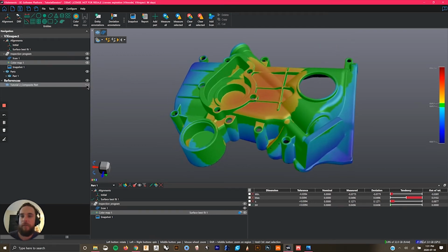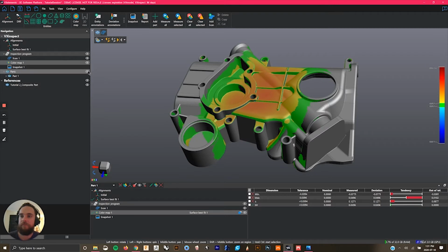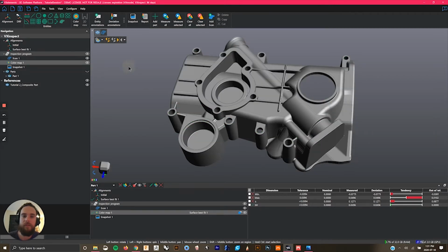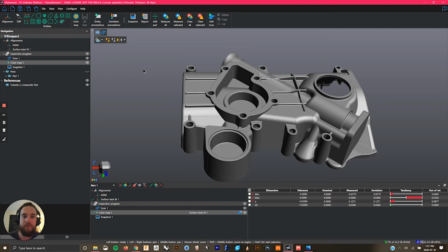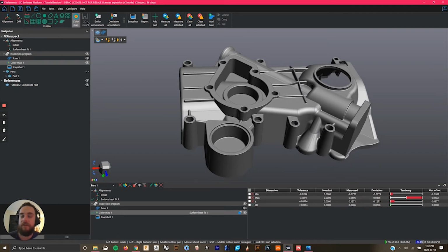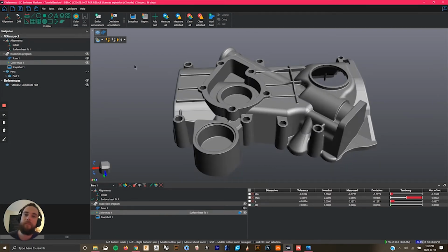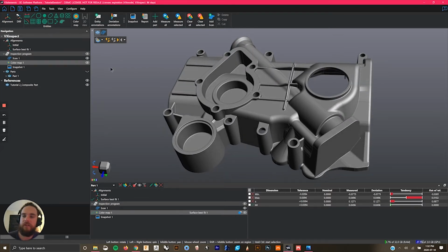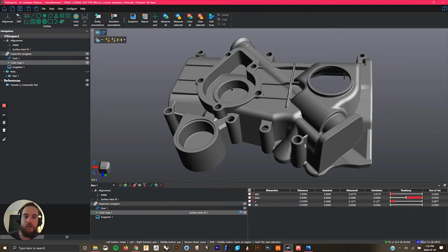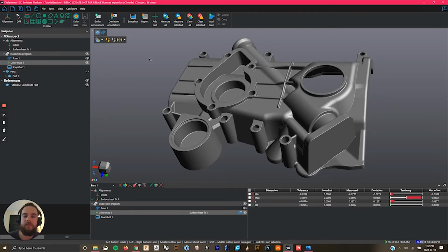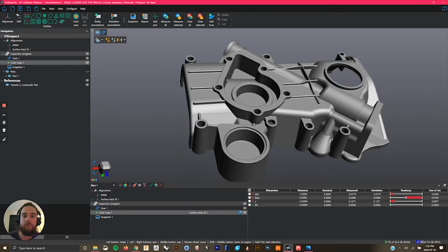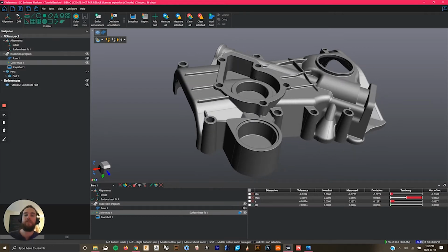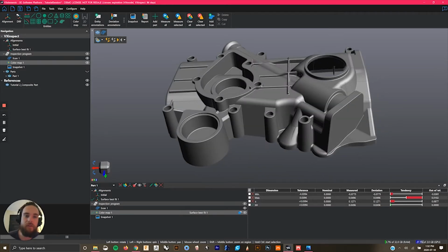So now that we have this color, we can start to potentially work on now just the CAD model and maybe hide our part for now, because the CAD model is going to be the chassis for which we ascribe these different shapes to report out on. So for example, the first thing we want to do is create some of the datums for this part based on a drawing. So the datums are the important features that everyone closely looks for and would almost align the part to in order to qualify its success.